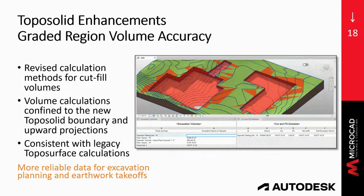Moving on to topo solids, the accuracy of the volume calculations has been improved. There is a new algorithm that is employing the boundary constraint method based on the new topo solid boundaries and projects vertically from the lowest to the highest surface point. This is eliminating the inclusion of extraneous volumes which were creating overestimations in previous versions.